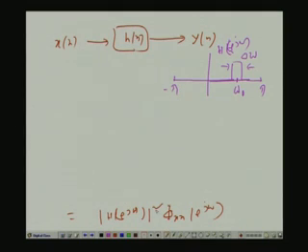If x[n] is passed through this, x[n] is complex valued, and of course, h[n] is complex valued, y[n] is complex valued, but the power spectral densities are real, that we have already seen. And what is the output power spectral density? That will be given by this previous thing, mod h e to the power j omega squared phi_xx e to the power j omega.